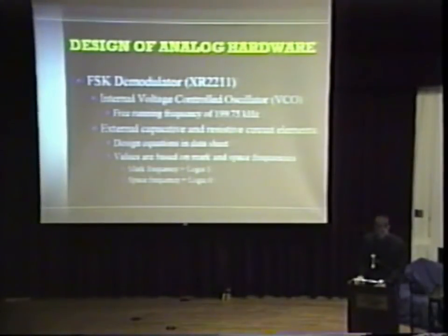For demodulation, I chose the XR2211 chip. Basically, this chip has an internal voltage-controlled oscillator of set voltage, and it allows you to design for a free-running frequency, which is basically when no input is applied. It's the frequency that the chip runs at. There are also several external capacitive and resistive circuit elements applied to the pins to design for filtering, and basically it's like a phase-locked loop system to lock onto the input frequency and provide a logic low or logic high output.